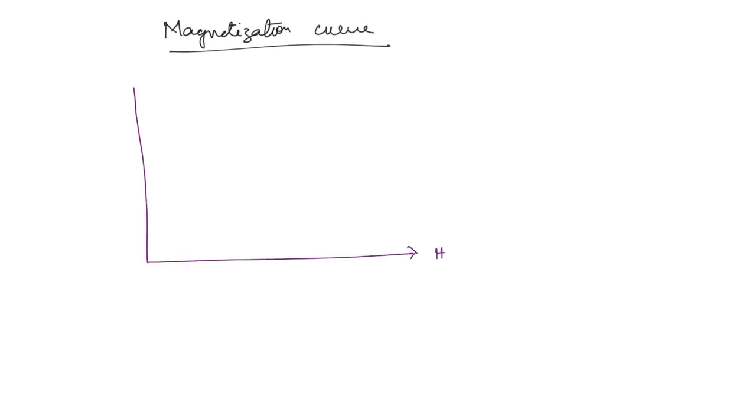And next we will discuss the magnetization curve in detail, because this is a pretty important point. So if you draw H, that is the magnetic field intensity, on one side, and the magnetic flux density on the other side. Instead of the magnetic flux density, sometimes you will find phi also, flux, and in place of H there will also be MMF. So the flux versus MMF curve will also be similar to the BH curve, because both are proportional, and H and MMF are also proportional.